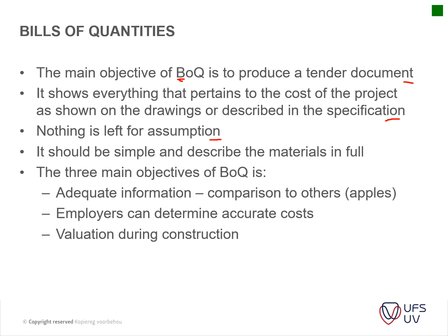So everything is measured. For instance, if there's formwork that has to be used whenever you're doing your concrete pour, for instance, if you've got a little bit of a chamfer at the edge on the sides of your concrete beams, that has to be measured in, or it has to be described in your item so that the contractor knows how to price for that.